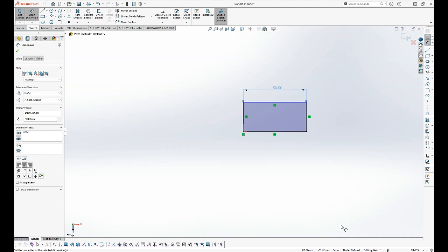So here you can see my drawing to be under defined. So this is another feature that you have to take note. So always remember that whenever you draw, make sure that it is always fully defined, meaning when it's underdefined, there's one side that needs to be measured.